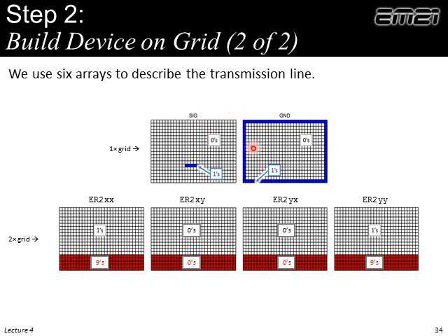but each array is describing a separate conductor. We have a signal, so this will be all zeros except ones right where the microstrip trace is. Then we have grounds, anywhere we want grounds. Well, it's obvious why we want the ground on the bottom, because our microstrip is sitting on top of a big ground plane. But I like also to put grounds all the way around. And when we use the Dirichlet boundary conditions, and because we're using these staggered derivatives, in fact, on one side it forces the potential to zero, on the other side it forces the electric field to zero.